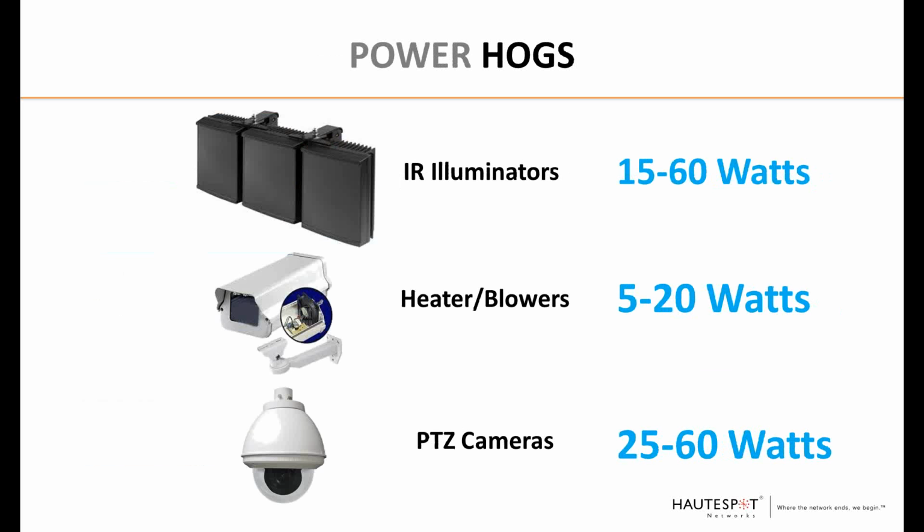A consideration here are power hogs. So keep in mind that some products have a lot more power draw than others. Typically, you'll want to stay away from PTZ cameras and large IR illuminators. Even though IR illuminators only kick on at night, you'll want to account for the maximum potential power draw when engineering the solar kits. And power draw that increases at night is one of the worst case scenarios, as there's no power being put back into the system as the batteries are being drained. So if the system is not engineered correctly, you'll have a power deficit, and you will have to remove devices or reduce the power load on the system for it to function as intended.